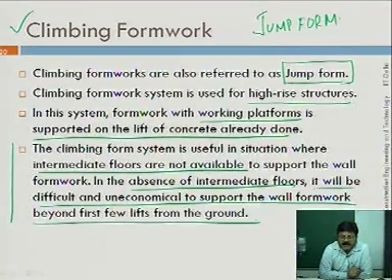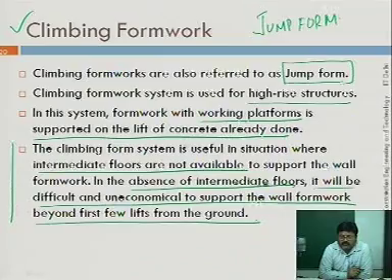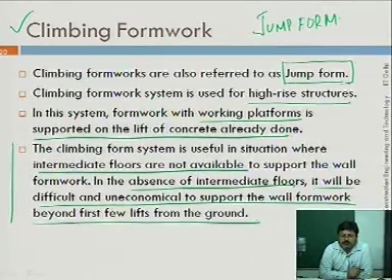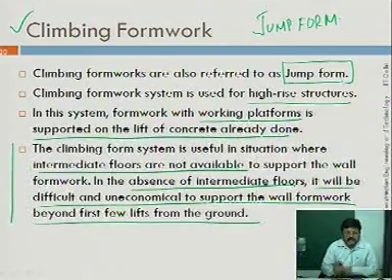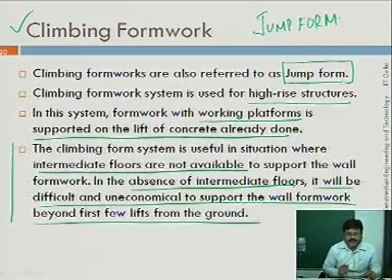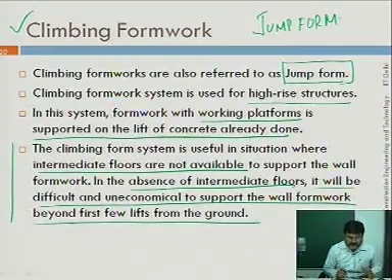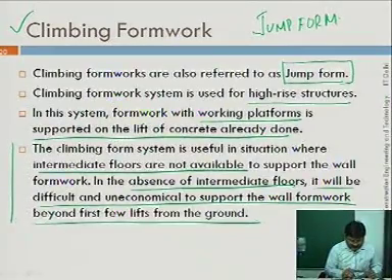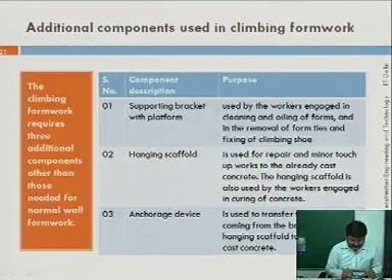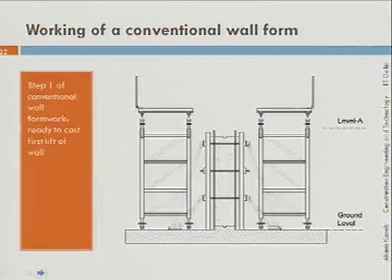Just understand for the time being that in climbing formwork, you are taking the support from the previously cast concrete. There is no need of erecting the formwork or the scaffolding right from the ground. Now I will tell you the distinction between the conventional way and the system of climbing formwork. Just see these pictures. Okay.